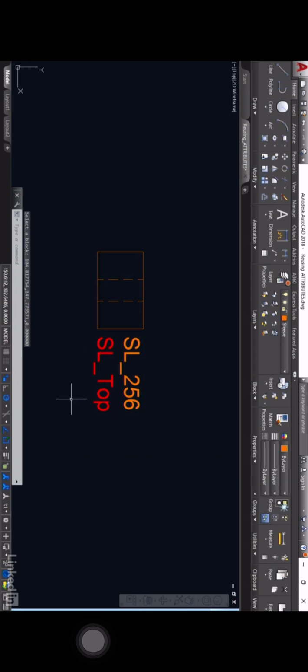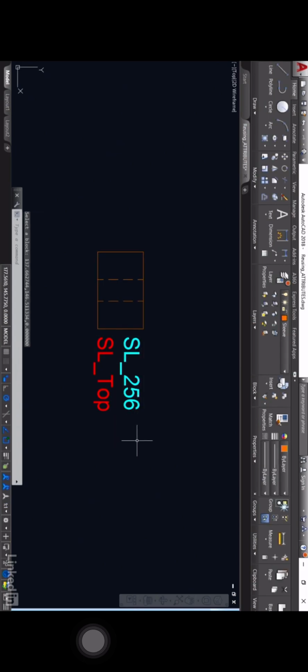So that's my tag for sleeve name. I change that to say red and I OK that. You'll see it goes red and you can differentiate it from the number of the sleeve perhaps. Or you might want the number of the sleeve to change. So you double click again, there's sleeve number, go to properties, we'll make that say a blue color. So let's go for cyan, for example, I OK that. And now you can distinguish the 2 attributes from the block, but they're still inside the block. So as you can see, when you're reusing design content, you can create blocks and give those blocks information using your attribute definitions.